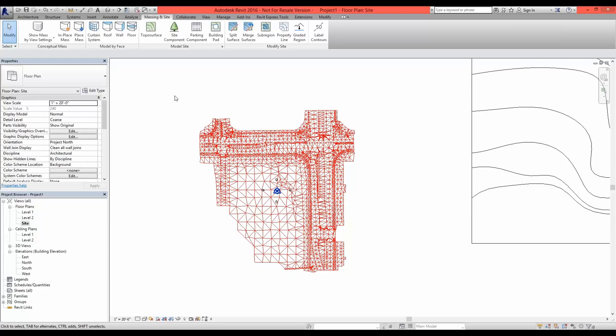often when you're importing this information in, before I mentioned that civil information often takes on real-world coordinates within whatever software it's being built in. So in Civil 3D, they will actually specify the geolocation on Earth where this topography is coming from, and possibly tie that to other GIS data available on the web or through different databases that they have access to. And so ultimately, when we bring this into Revit, it may not place it directly at our origin.